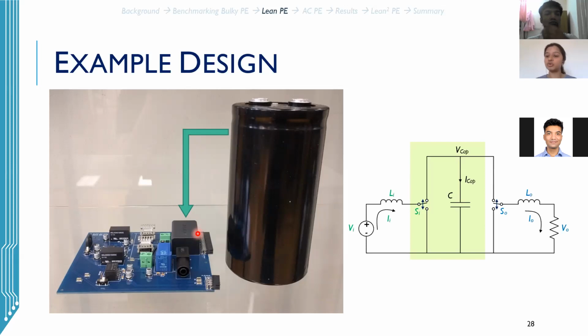Now, as we move to a smaller capacitor value, and we are really looking at high density power conversion, we can also introduce such cooling schemes such that we do not need a bulky capacitor, but we can do with a small capacitor, which ensures stable operation, high performance operation, and is still smaller and can handle the ripple current.